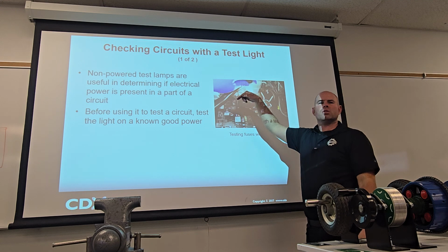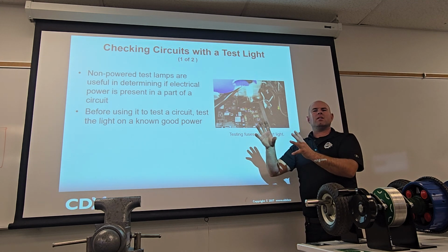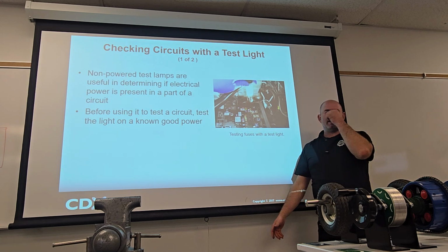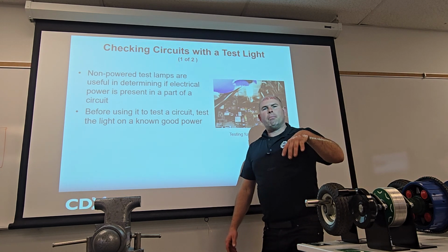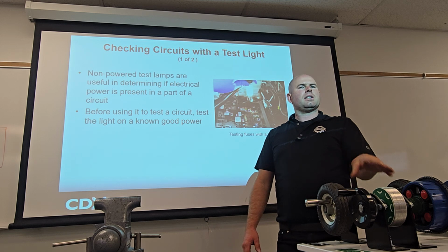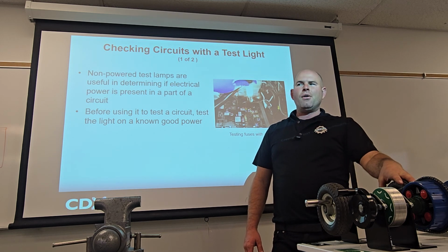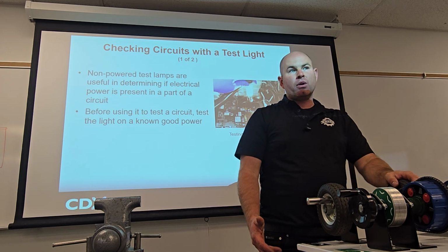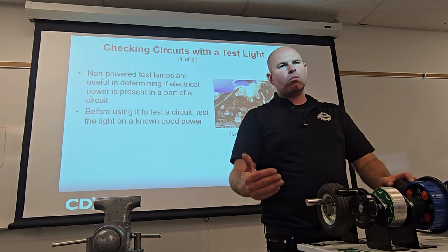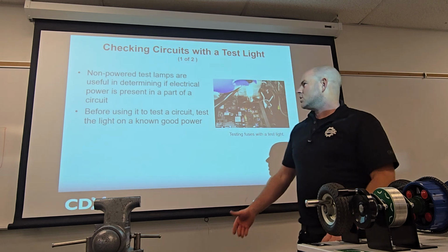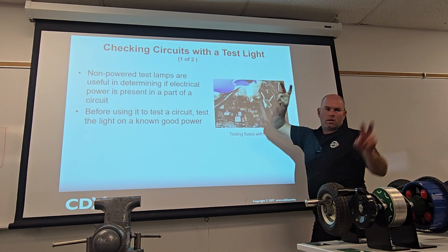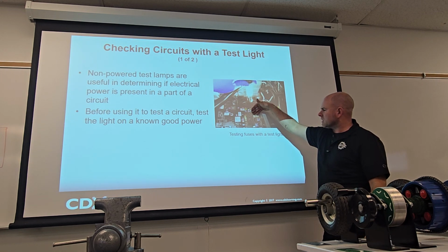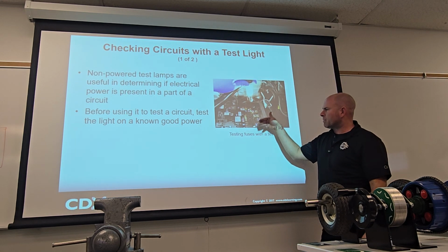So if you have 12.6 volts of available voltage, your meter would read 12.6, right? What would the test light read? Exactly. So it doesn't give you as much information, but when we're diagnosing a circuit, let's say a tail light bulb is out, I don't really need to know if the connector is dropping like 0.1 volts or 0.2 volts. I'm looking for something where it's dropping like 12. So a test light would be like, okay, I'm going to use this loosely: I have power because it's lit. I don't have power, I dropped it between 2 points.